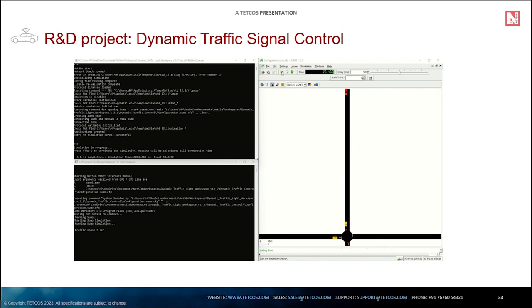A better option is to precisely measure the distance of the emergency vehicle from the signal and then first keep the EW lane green to prevent vehicle pile in that lane. And then at exactly the right moment switch the NS lane to green for the emergency vehicle to pass by. This is possible because we can process the vehicular data collected by the RSU that is near the signal.